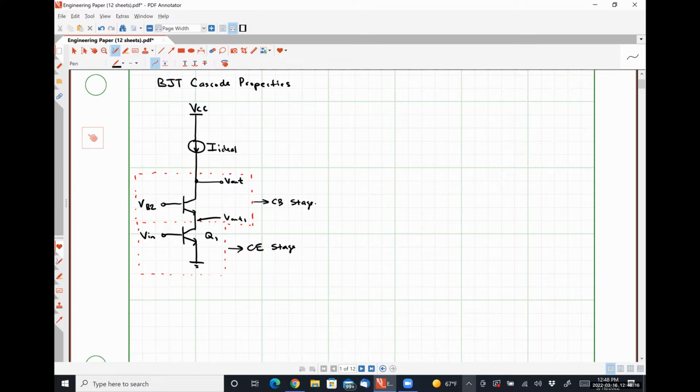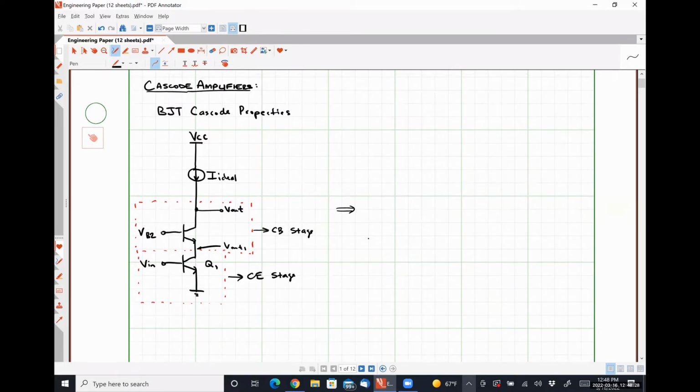All right, so our small signal model for this guy is going to be a bit ghastly because it's got two transistors in it. So I'm going to start here. So this is our input signal feeding into the base of transistor Q1. I guess I should label this guy Q2. Here we have our resistance r pi 1. And so this is voltage VBE1.